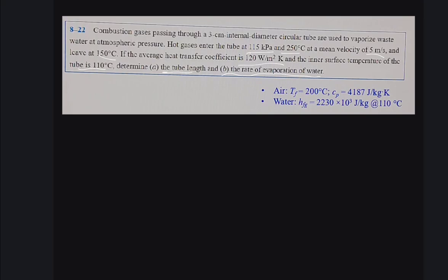We're given some of these other numbers over here that may be beneficial to use, and I'm going to throw one more on there, this gas constant R. Because these are gases, we can actually use the ideal gas law to solve for density. So that's what we're going to do first. So density is P over RT.